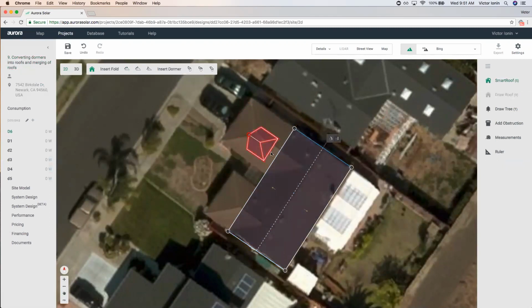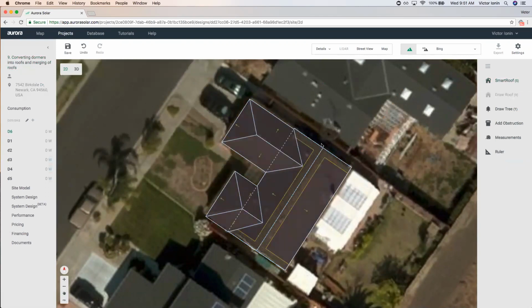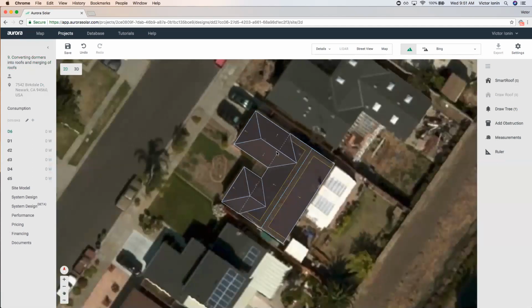I'm going to click on the hip dormer, three steps. Click once to put the anchor node, resize the dormer, slide these center nodes in. Let's try that again. Hip dormer, step 1, click. Step 2, resize. Step 3, slide these in. And then you're done. By drawing this roof in sections and using something like a dormer tool, you can make this home easier to draw.